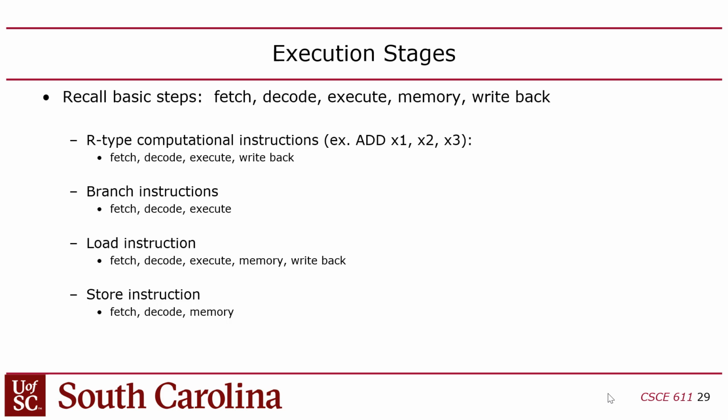So what's decode? What happens in decode? Do you guys remember decode? Yeah, that's right. The instruction comes in from fetch, and then in decode, it breaks out the instruction into control signals, right? But it also accesses the registers, reads the registers too.